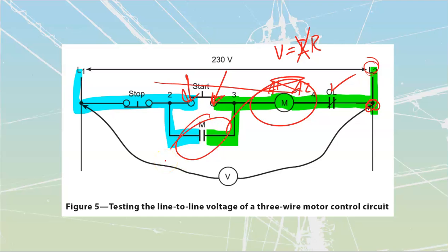On some of my NEMA-style contactors, these are going to be done off an auxiliary block that's mounted on top. Check that thing has not vibrated loose or been disconnected, that the physical contact is still tied to the armature that's pulled in, and just meter it up. Disconnect the wires from it, meter that thing out, make sure it's going to be good to go.